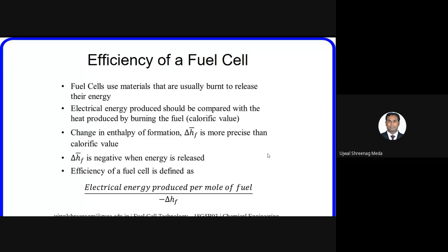Enthalpy can be more or less compared with the calorific value of a fuel or chemical energy of that fuel. That consists of two terms, that is Gibbs free energy and entropy. This Gibbs free energy is the useful part of the enthalpy. Entropy is the part which cannot be utilized.